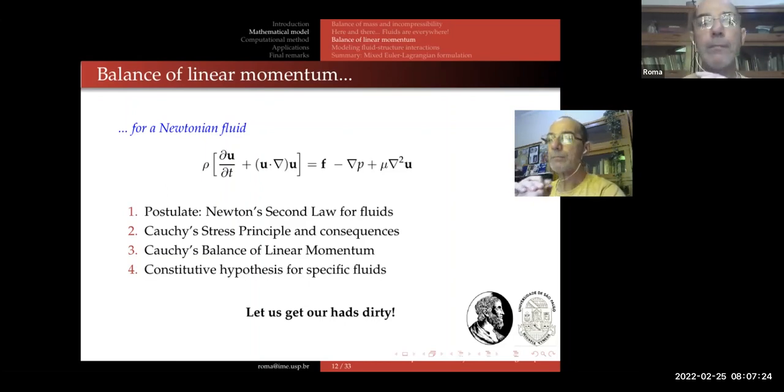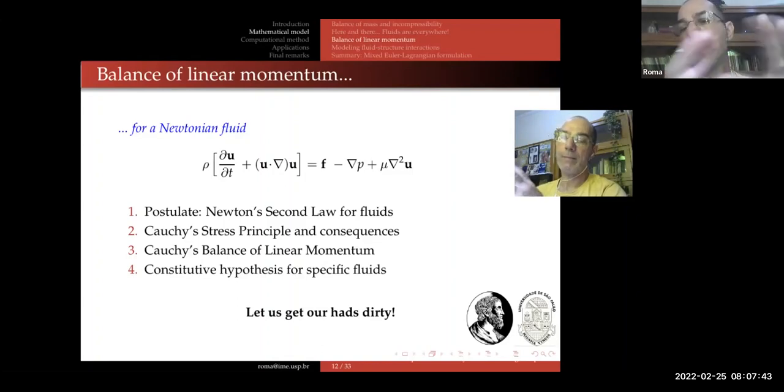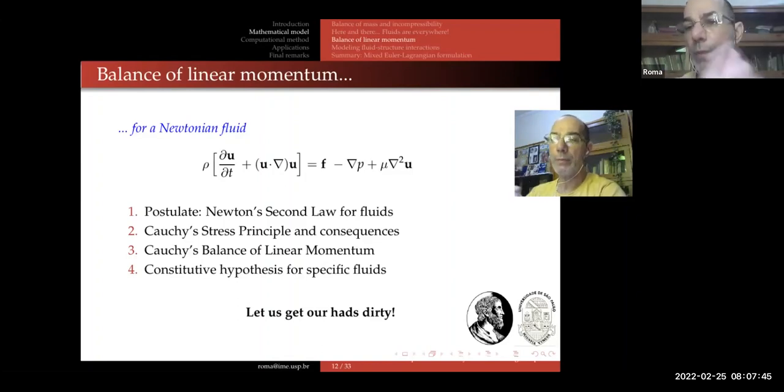Based on these two sets of undeniable truth assertions, we arrived at something called local equilibrium for the stress forces.